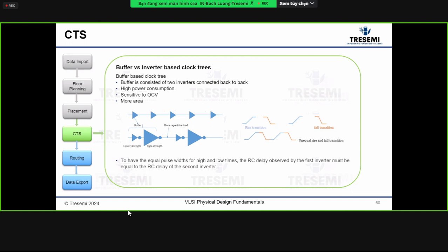But yeah, basically that's what it comes down to. You get more logic, more paths, so there's more chance of OCV, more nets, more cells that go through. So the more chance of OCV impact, therefore it's going to impact your skew also.